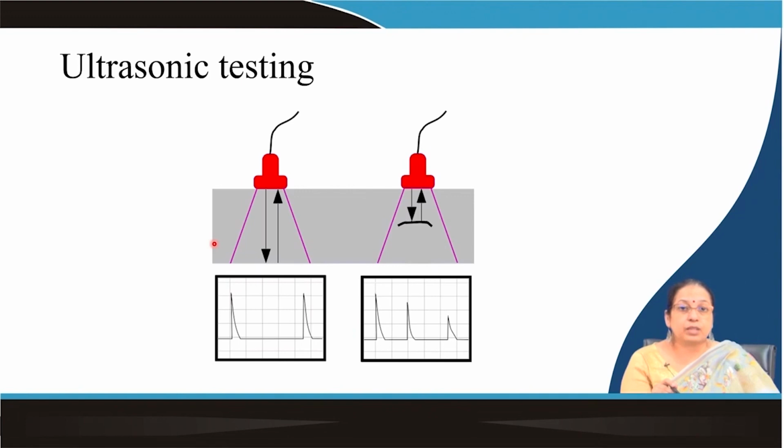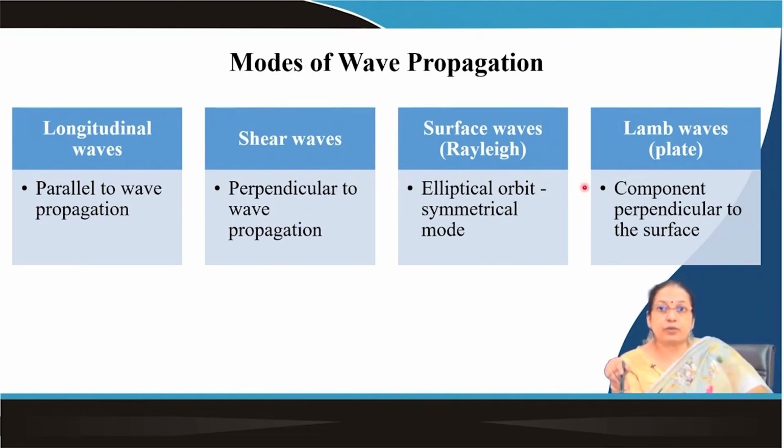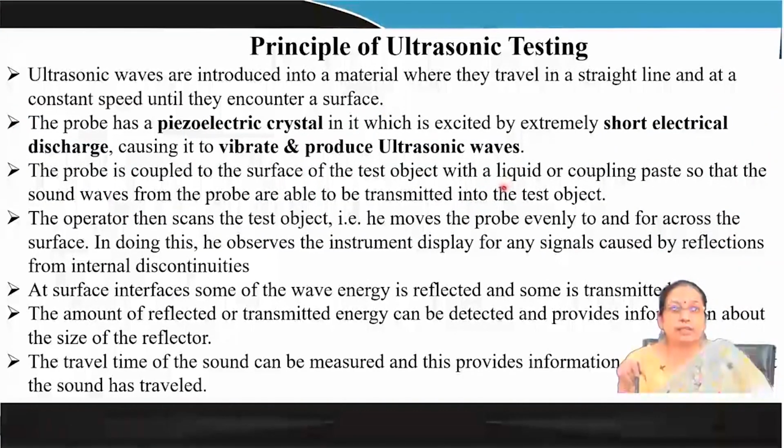the eddy current based technique. So, finally, ultrasonic testing is a very important technique where you basically apply ultrasound, and from the ultrasound signal you determine the defects present in the material. Whenever you are detecting, you are basically just applying ultrasound. It may be longitudinal waves, shear waves, surface waves or Lamb waves. So, any kind of waves can be applied.